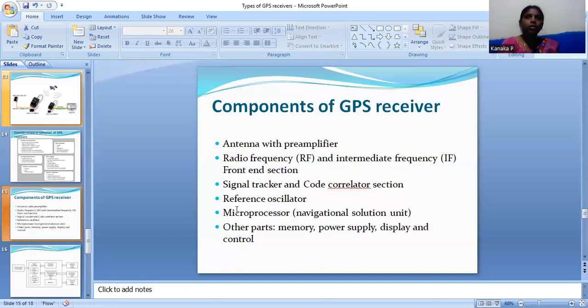Next, total station advantages and disadvantages. The advantages of a total station are the following. First one is setting up the instrument quickly on a tripod using a laser plummet and an onboard area computation program to compute the area of the field. For quick visualization, a graphical view of the plots is available. Integration of databases and old maps is done automatically.